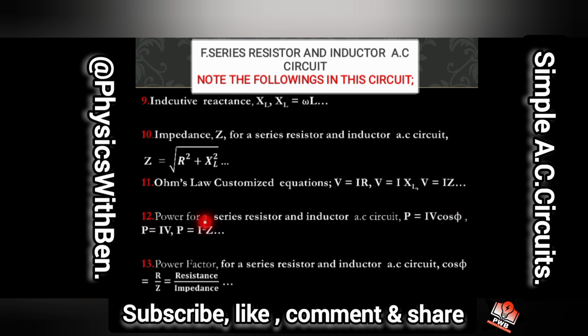This and this can be used to calculate the power in the circuit, where cos phi only stands for the power factor. And in this case, cos phi here is equal to R all over Z. This is it here.